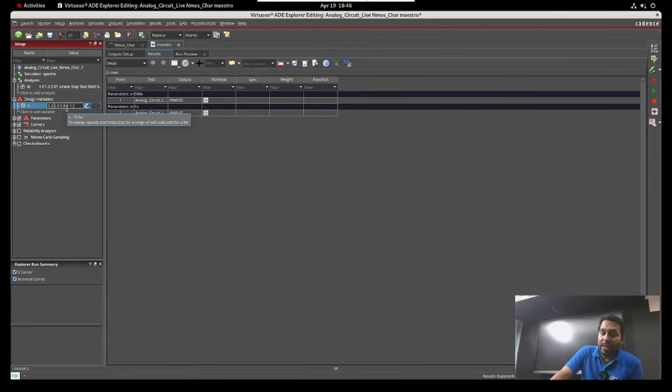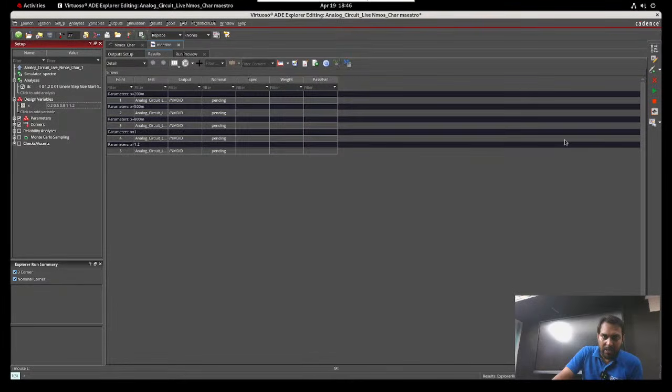On the basis of that, what will be your current? Just run it and check what the drain current will be with respect to VDS, where VGS is 0.2, 0.5, 0.8, 1 volt, and 1.2 volt. On the different values of gate to source voltage, what will be the graph of ID versus VDS?